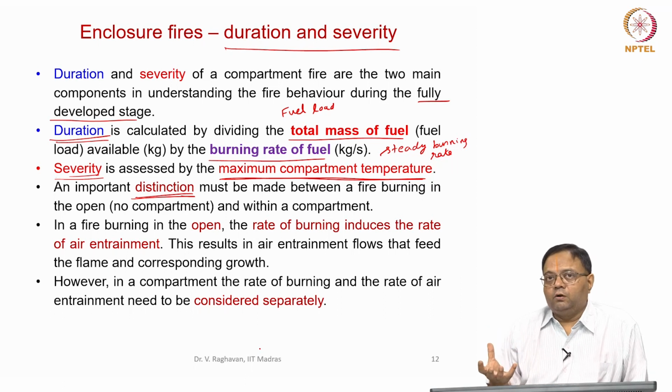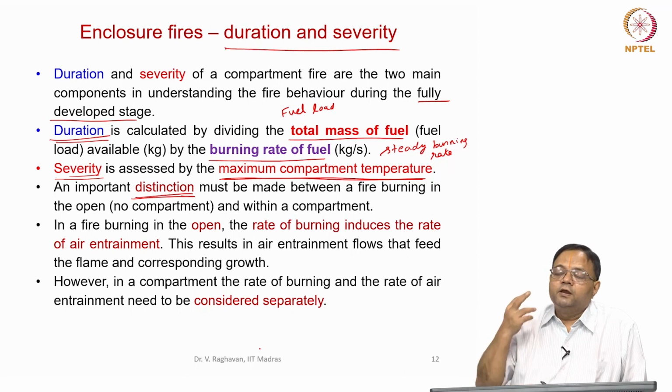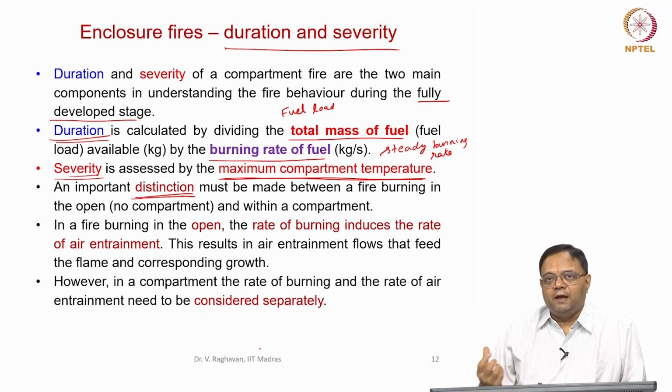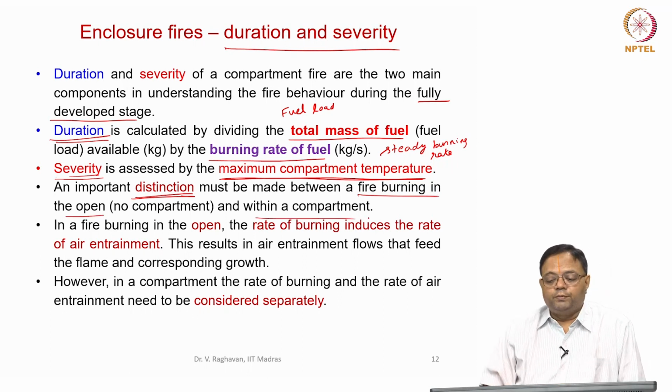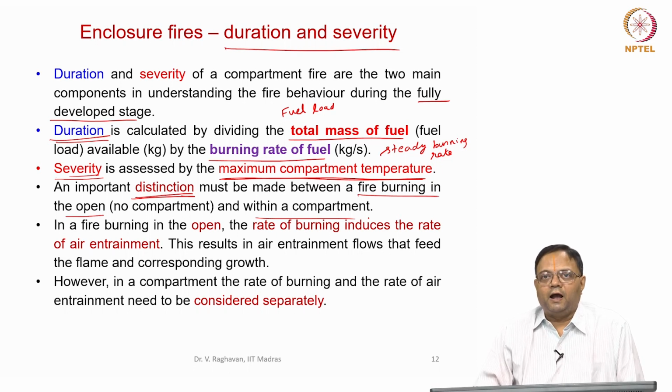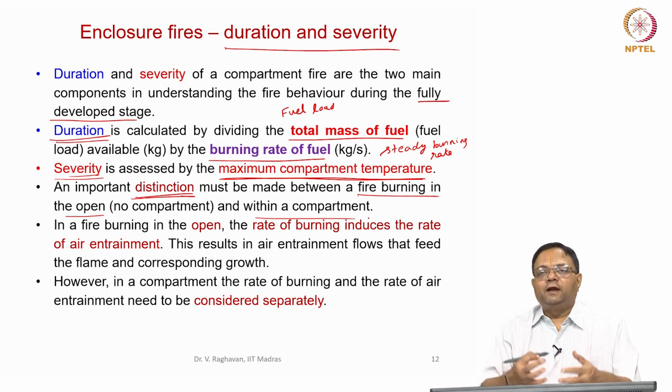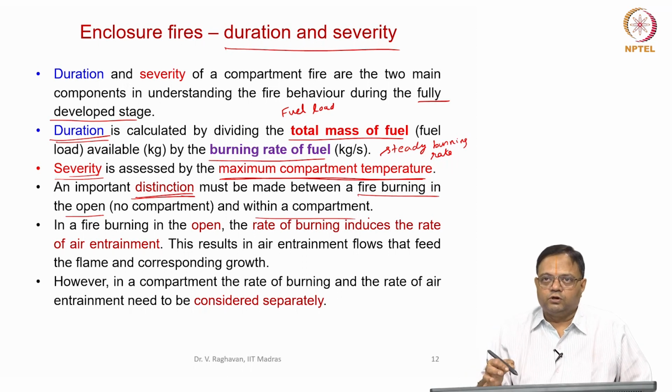So, when a particular fuel, solid fuel or liquid fuel, any other fuel burns in open environment, it may have a certain burning rate, but the same fuel, if it burns within the enclosure, the burning rate may be different. So, the difference between the fire burning in open or within a compartment has to be made. That means some flammability characteristics of enclosure burning has to be determined. For that, already we have told that there are standards to create an enclosure and burn commodities in the enclosure to understand the burning behavior of the commodities within the enclosure.